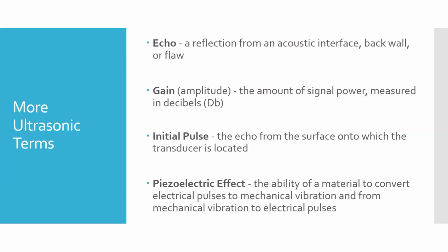Echoes are where sound reflects off of an acoustic interface. So I put here acoustic interface, and again, those could be, every time the sound goes from the epoxy to a fiber, that creates an acoustic interface, and that creates echoes. The back wall of the part itself is an acoustic interface between the part and the air, and you're going to get an echo off of that.